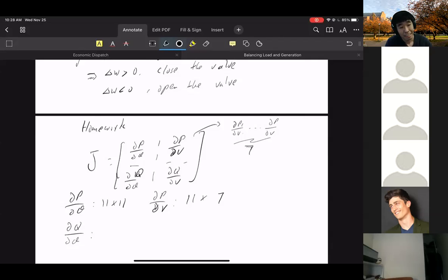What do you mean by ignore the Q? Like the generator only generates the active power. No, a generator generates both active and reactive power. Yes, right, so you ignore it. Q is definitely not 0. It doesn't mean there's no Q. There's always some Q within a generator. What I mean is you don't know the value of the Q at the beginning of the problem.